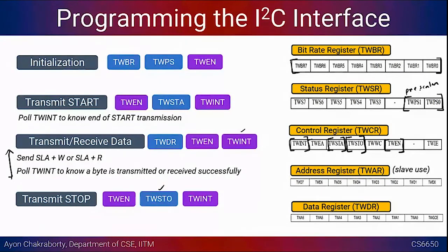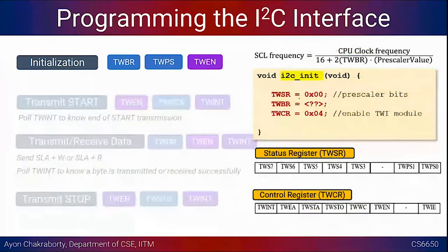and then there would be a lookup table, given that you have 0 0, 0 1, 1 0 or 1 1, what is the corresponding value you can get. And apart from that, you will also have a value which is the byte that is contained by the TWBR register. That you can set, so that's why I put a question mark. So you can put that particular value whatever you wish. Same for the prescaler bits.